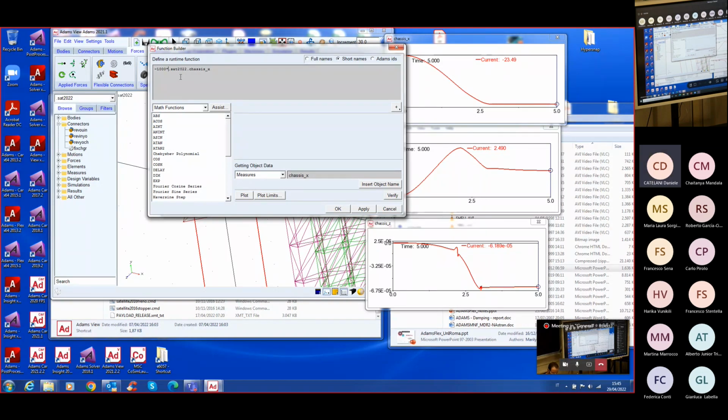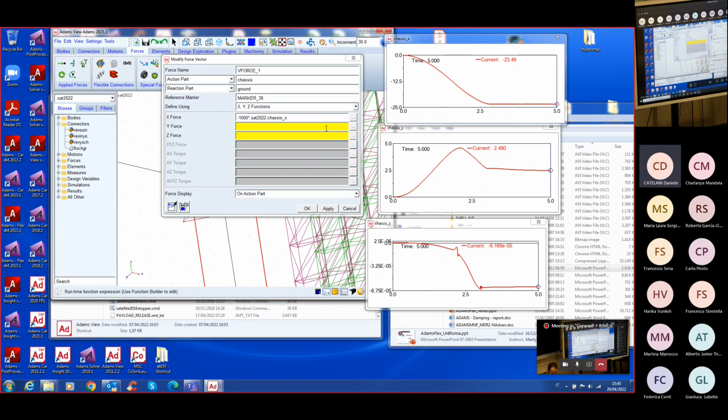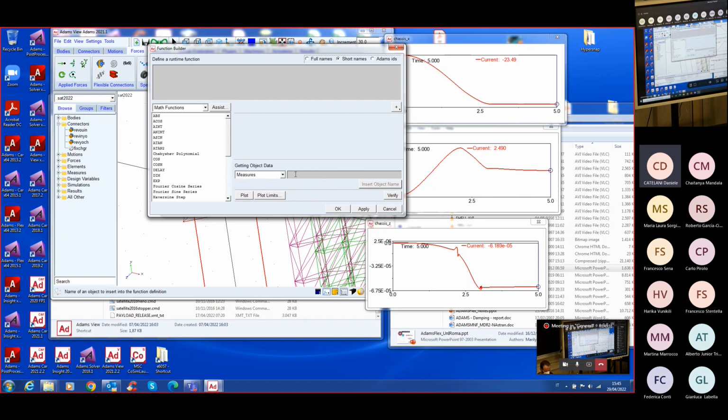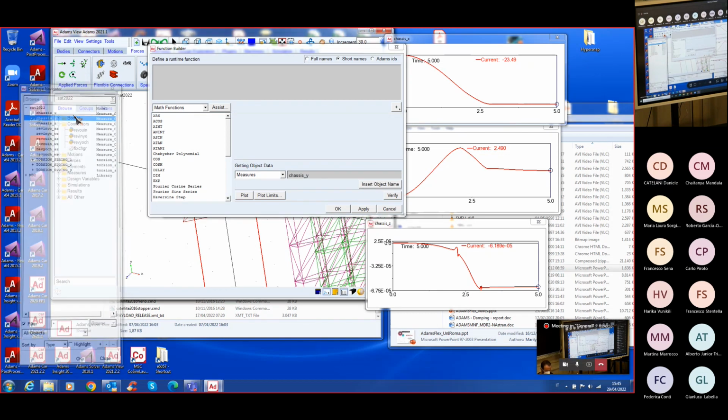In my control system, I have to tune, to calibrate this gain. This is a typical function to reduce the error along X, a proportional controller. The same for the Y.